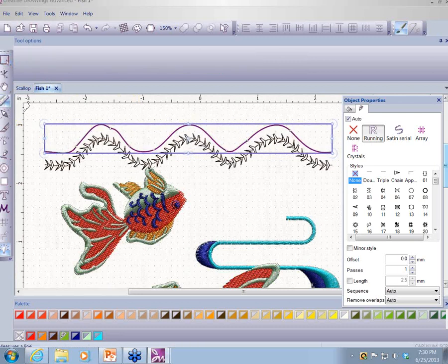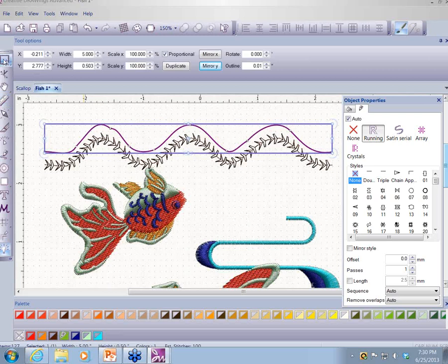And go back to my measuring tool, measure. All right, that's pretty close, 0.249. All right, so that will work for me. I'm going to go back up to my rectangular selection, and that will tell it I'm done with the measuring tool. It's just to finish things off. If you're working with some of these tools, it tells the software we're done.